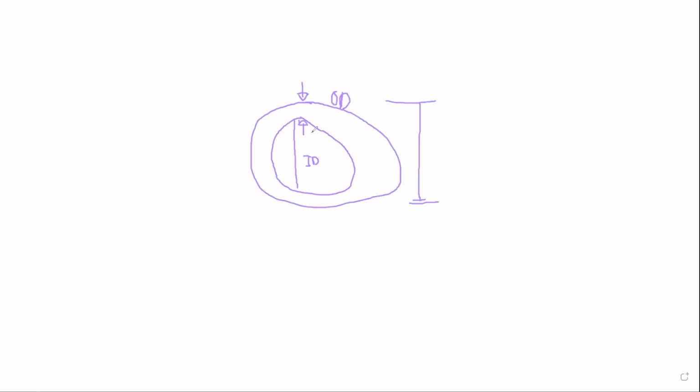So when we design a water supply in WaterGEMS, we basically provide an internal dia. Based on that dia you select a pipe available in the market. So for example, if you design a 300 millimeter pipe, then you have to select a pipe that should have an internal dia of 300 millimeter, or it should be greater than that.